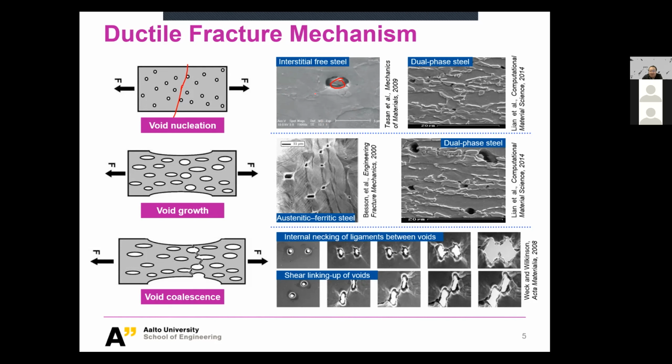The soft medium will be easy to deform, and the hard one doesn't deform that much. So you will develop an inhomogeneous deformation. And that's the reason we would develop some voids. Look at it here. These are the origin of the voids.